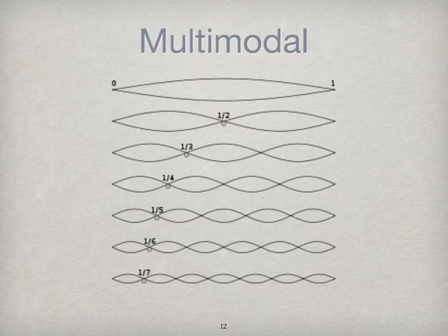Inherent vibration modes in structural components or mechanical support systems can shorten equipment life and cause premature or completely unanticipated failure, often resulting in hazardous situations. Detailed fatigue analysis is often required to assess the potential for failure or damage resulting from the rapid stress cycles of vibration.